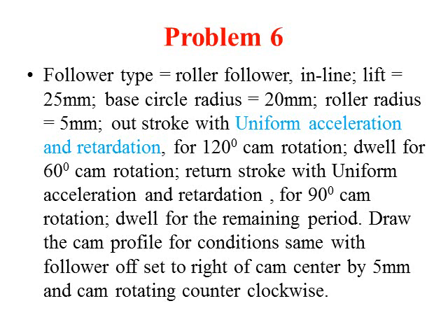They ask to draw the cam profile for the condition, with the follower offset to the right of the cam center by 5 mm, and here the cam is rotating counterclockwise. So, very important, it is clearly mentioned: in the problems we have solved so far, the cam was rotating in the clockwise direction, but here the cam is rotating in the counterclockwise direction, with the follower offset by 5 mm to the right of the cam center.